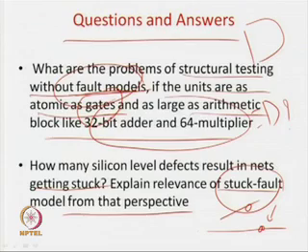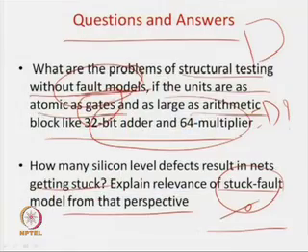Because the question is, these nets in the circuit do not really have such a neat stuck at 0 and stuck at 1 fault, because in the real world there are defects like the net may be torn, the net may have become thinner and so forth. But still, why is the stuck at fault model so relevant, if it is not really happening at that level? So, these are the two questions we are putting into the picture. We can go through the lectures and then think over them, and in the next lecture, before we start it, we will go for the answers. Thank you.